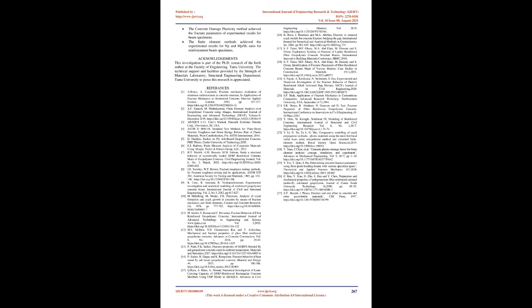Nonlinear finite element method based on advanced 3D models is a relatively economical and powerful tool. The finite element results can be effectively used to simulate the true behavior of reinforced concrete beams even under complex conditions. The crack pattern given by finite element model is almost similar to the experimental ones, with the same trend of the low displacement response. Damage for traction separation laws is the best method to represent the fracture mechanics model, which achieves the experimental results.